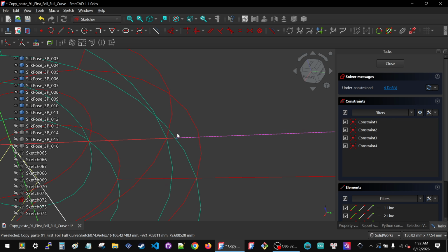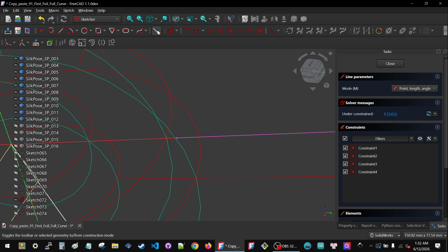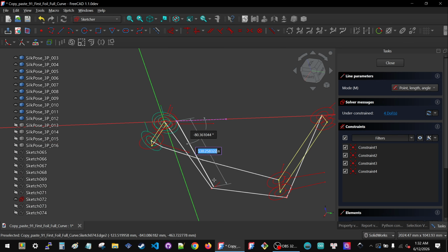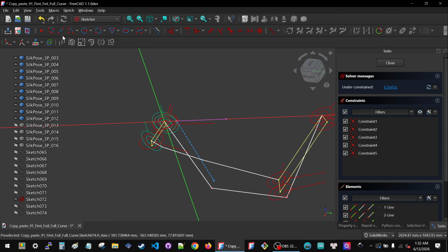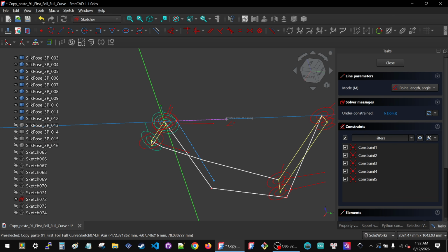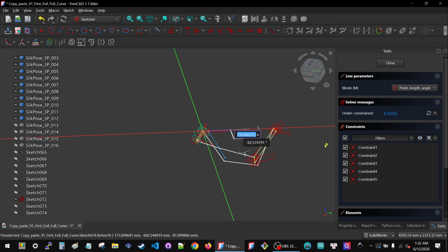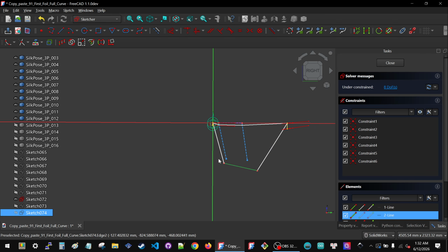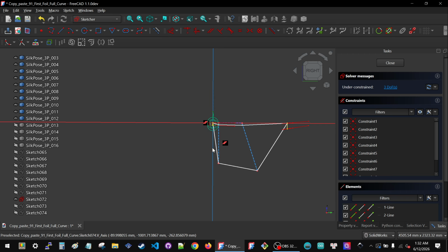So make sure you find this point, start the line, construction, find this point, clip it. We're going to clip it down below, one more line. Let's give it a shot. Will it let me connect? Yes, it let me connect. Okay. Go back to the right view. Box select these two, coincident. Box select these two, coincident. This guy, y-axis, parallel. Y-axis, this guy, parallel.